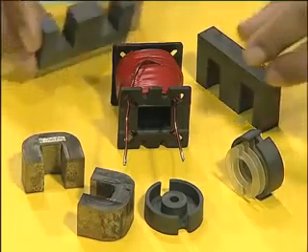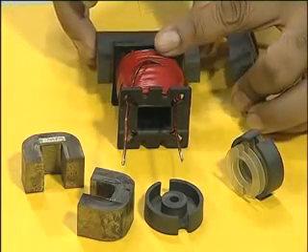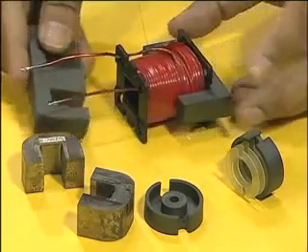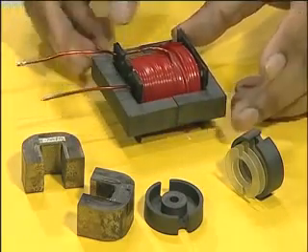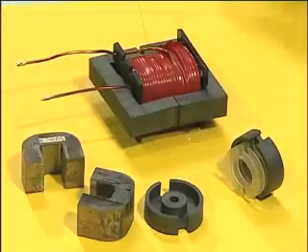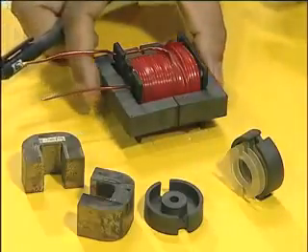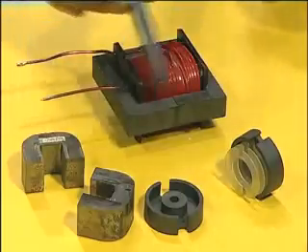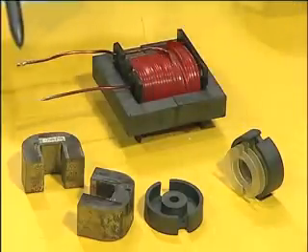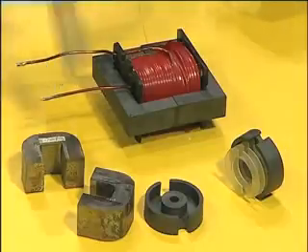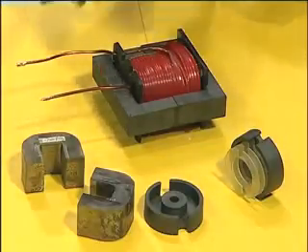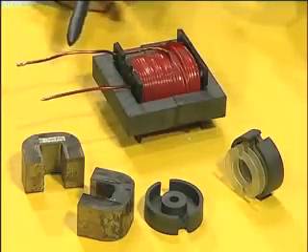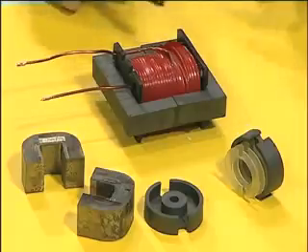And after winding, you take this core, put it like that, and assemble it in this manner. So, this becomes an inductor with a ferrite core. So, this is a ferrite core. You have one end of the winding here, another end of the winding here, goes through this coil, there is a bobbin, this bobbin is fitted into the core, this is a ferrite core, ferrite EE core.